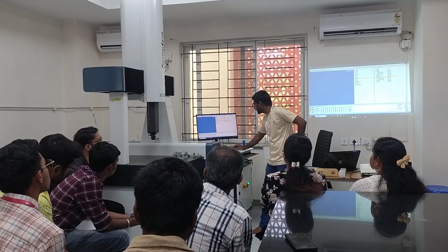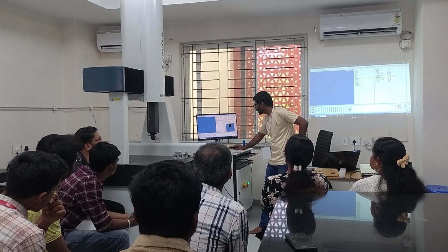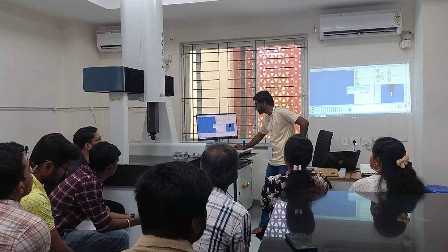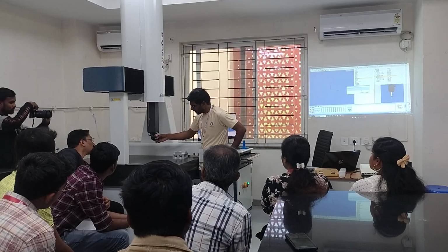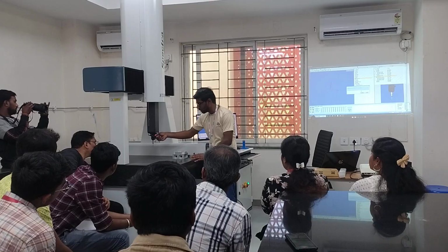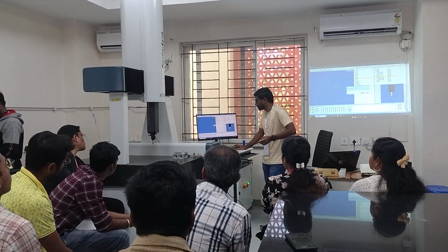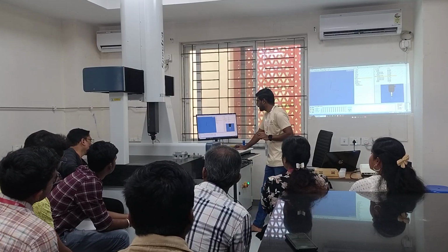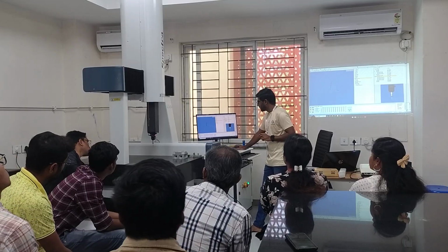Currently I see that A0, B90 is activated. If I right click and activate, it means 0, 0 is getting activated. It is telling me please rotate the sensor into A0, B0. Okay, I just loosen it. B0 is already there. I loosen it to A0 and I have locked it. So now A0, B0, I have to rotate and I have done it. Then it is telling something, no. So it is already accepting it. So this activation, deactivation can be done.